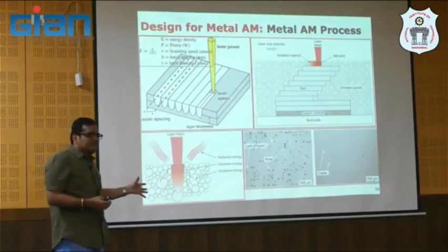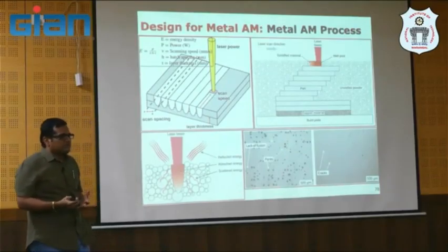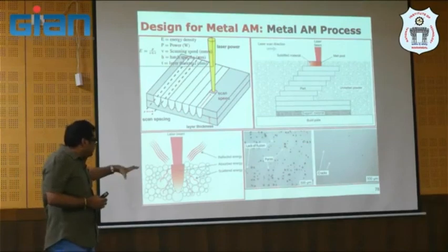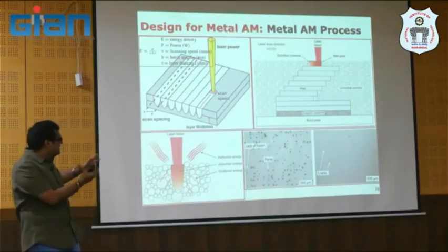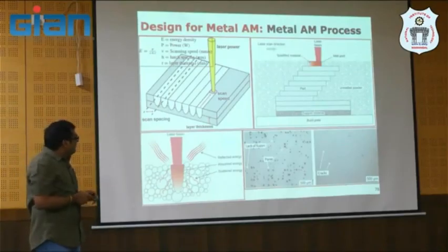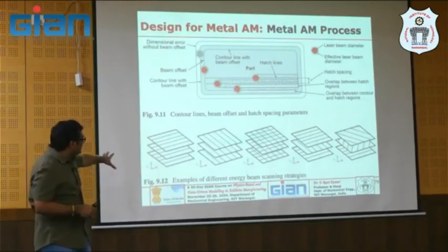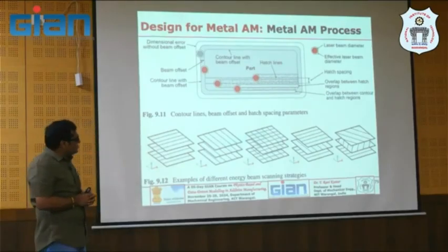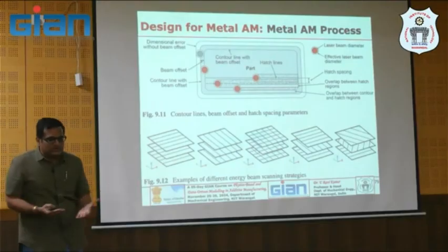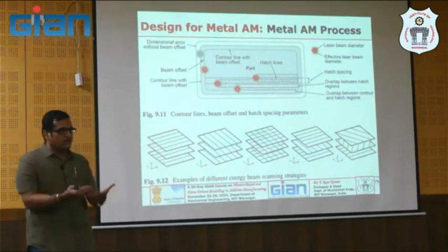Different materials have different photon absorption, right? I'm not going into the deeper aspects of that. You have absorbed energy, scattered energy, reflected energy, and all that. The major part here is how you make use of your scanning strategies, so as not to allow residual stresses to accumulate at a region or a layer, right?